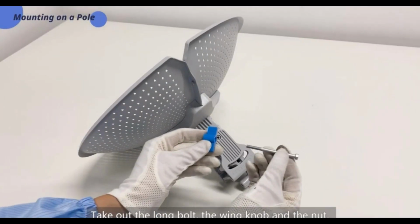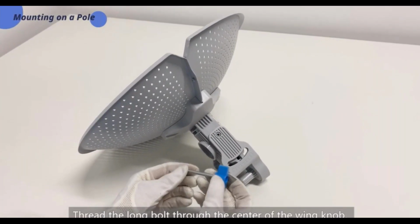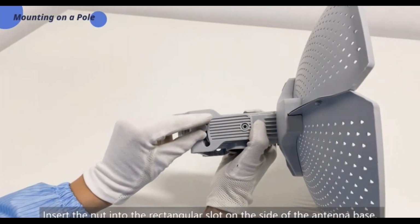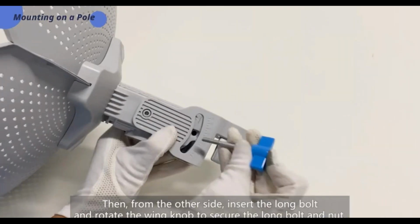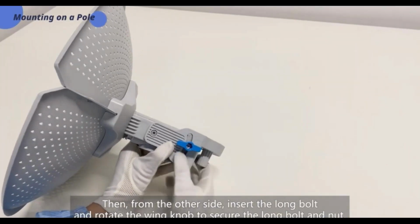Take out the long bolt, the wing knob, and the nut. Thread the long bolt through the center of the wing knob. Insert the nut into the rectangular slot on the side of the antenna base. Then, from the other side, insert the long bolt and rotate the wing knob to secure the long bolt and nut.